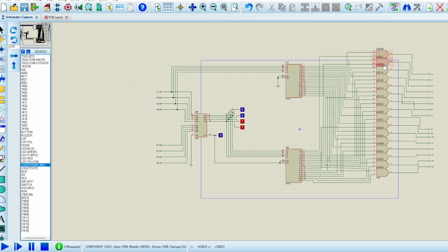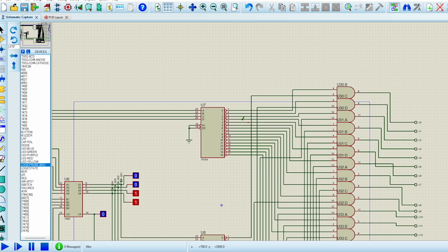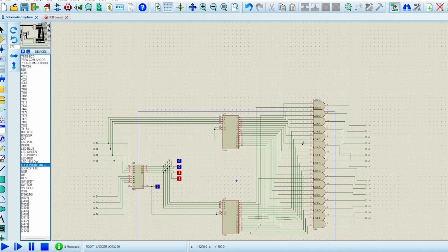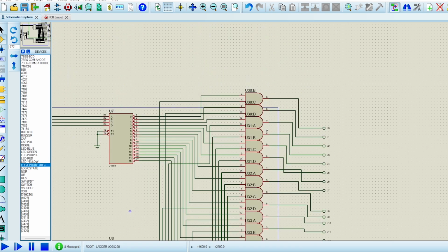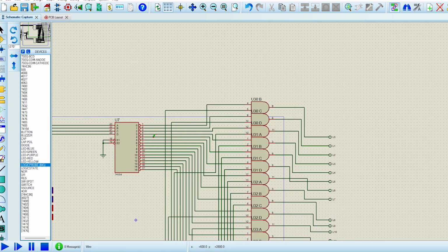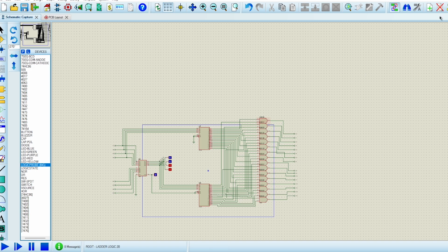The way it works, because we used so many AND gates here, is that the LED on the board module acts as an active low operation. So we need value 0 for the particular position that is shown here. Let's say the player's position is 3. So I need value 0 for this position 3. How do we get that? If there's any position here in 4, then the others will be 1 and the 4 will be 0. That's how we use AND gates to eliminate all the other 1 values and give the 0 value for this exact position. That's how the ladder position works.